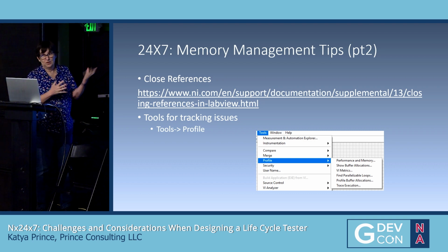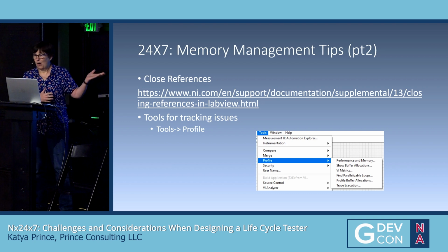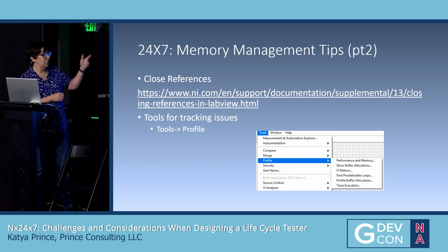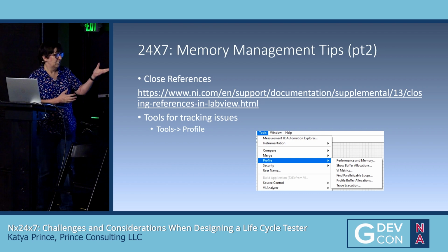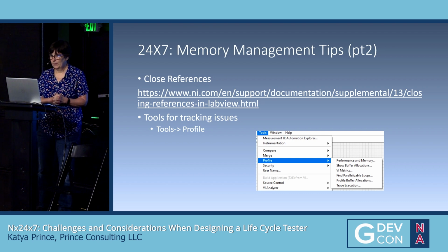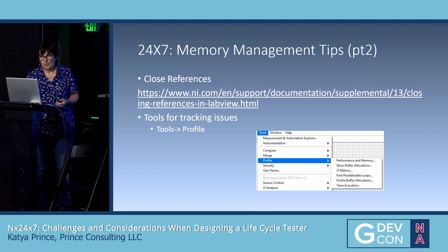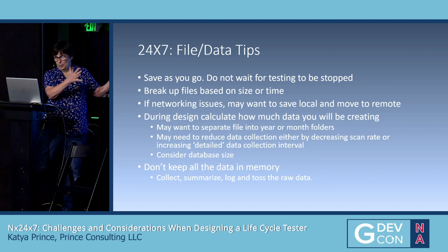And memory management, it can be the trickiest one. It's the hardest one to sort of test and debug. So there are tools that can help you out with that. If you go under Tools, Profile, there's a whole series of different tests and tools that can allow you to statically analyze and dynamically analyze your VIs as you're running. Okay. So that's general memory management.